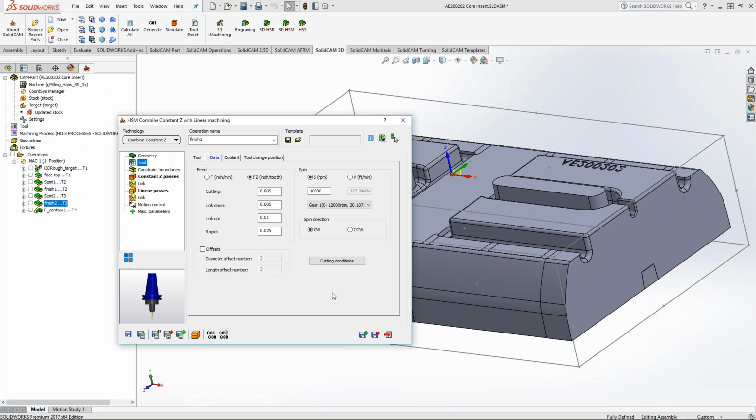What does that tool kind of look like? The tool that I used to burnish with? Yeah. Actually, all I did was I took a 2-flute 3/4 ISCAR insert mill, and I just ran the surface footage way up, and just took very light cuts, maybe 2/10.